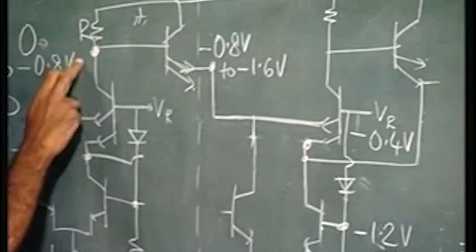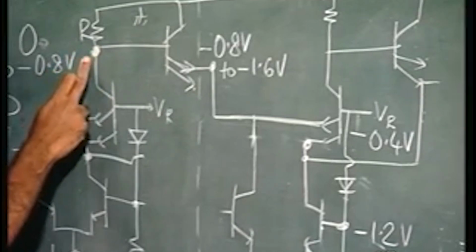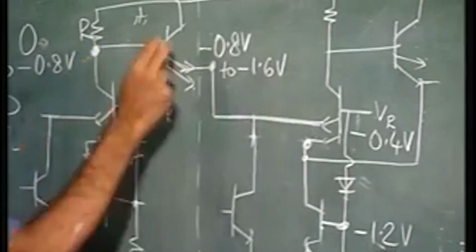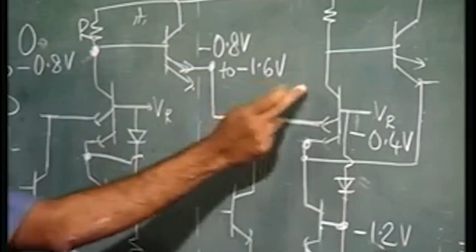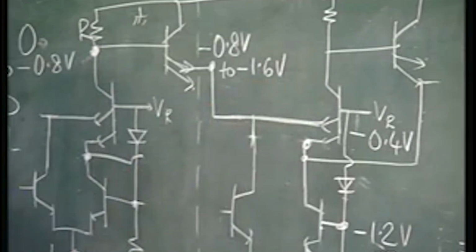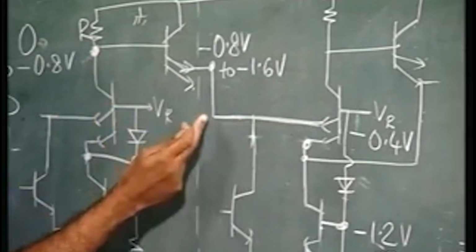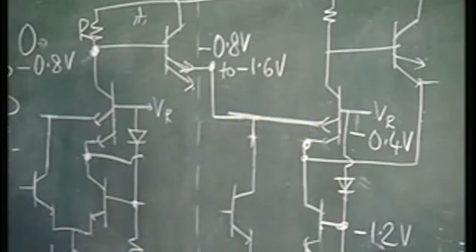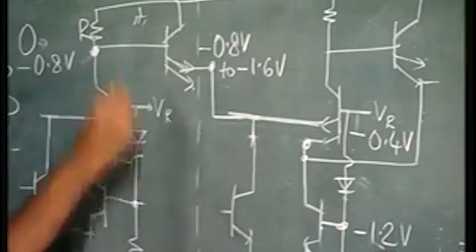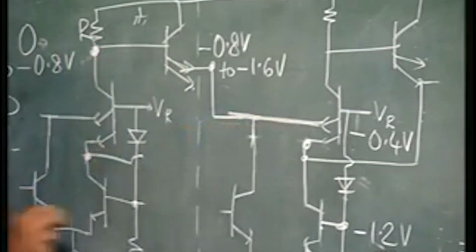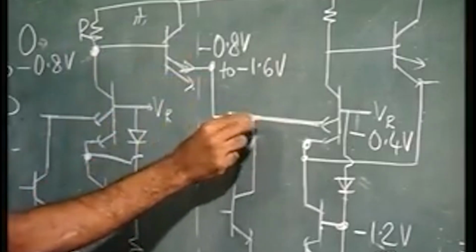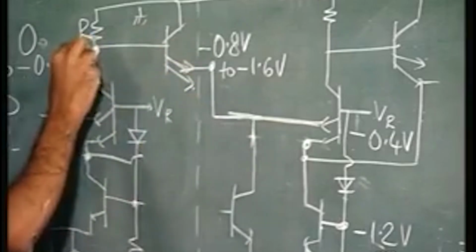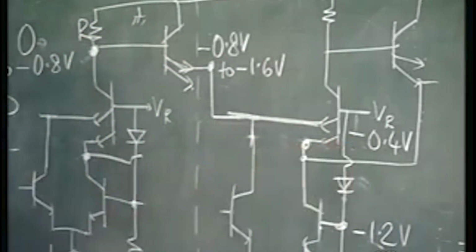So, if this voltage here is 0 volts, what happens? This transistor is on and this transistor is off. So, that is what we have said. If the input is high, then this transistor is off. So, between these there is perfect voltage compatibility. You can feed this output directly as a direct input here without any level shifting necessary, because this voltage varies about the reference voltage here.